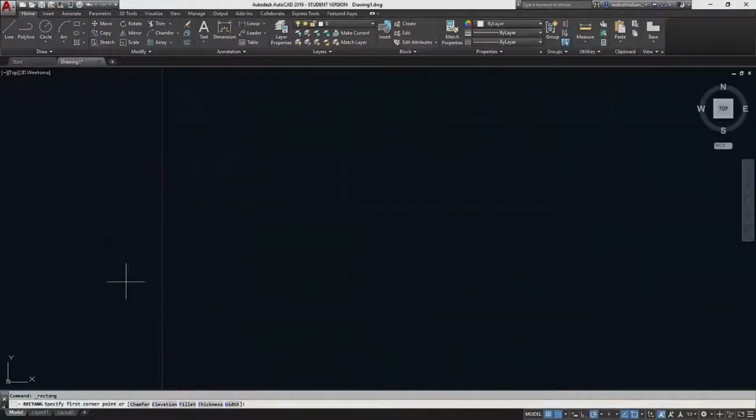You'll notice a difference as soon as you start scrolling your cursor across the screen, because now it will jump across the grid points. That's because we got the grid set at a 1/2 inch, that's the default, and it will jump every 1/2 inch. So if we go somewhere down on screen, it doesn't have to be on that line there, it could be anywhere, say there, okay, and pull that away. We could effectively count 1/2 inch, 1 inch, 1.5, 2, 2.5, 3, 3.5, 4, and then do the same thing going in the upright direction to get a 4x4.